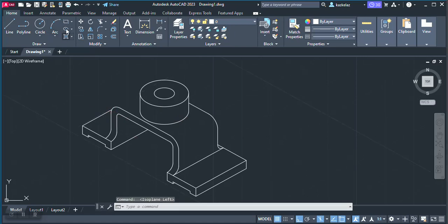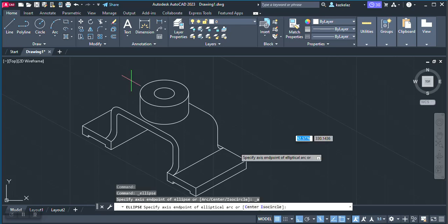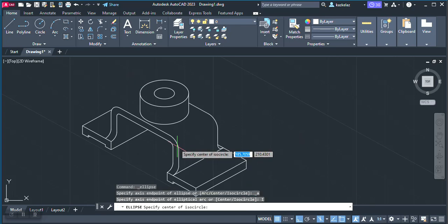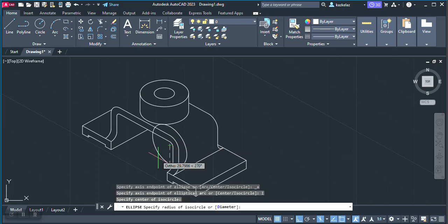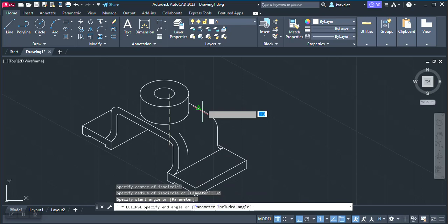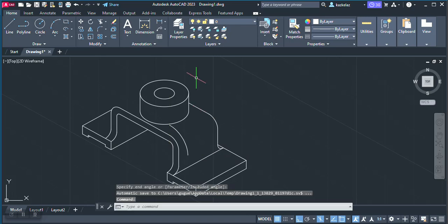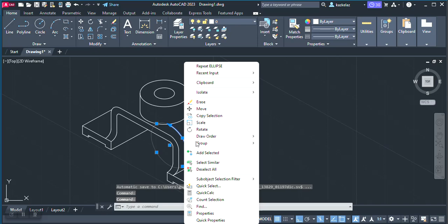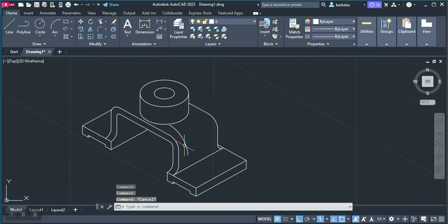So from this line, I know it's 68. I know that the midpoint would be 34. Since it's 34, I need to move to 29, which is back a bit. So I'll need to copy, select. The other one is at 39 because they are 10 mm apart. So from there, I'll go 29, then the other one is at 39. Yeah, and we have something like so. Let's remove this part. Now we have the arcs that we have there, right?